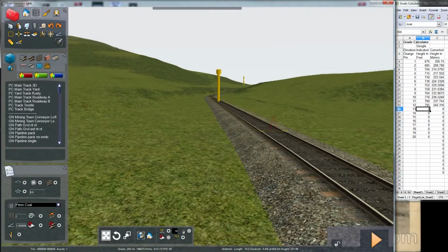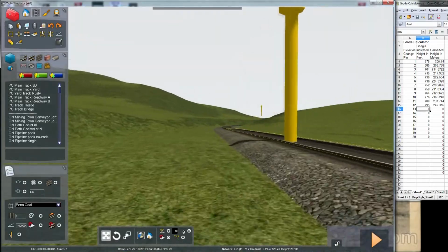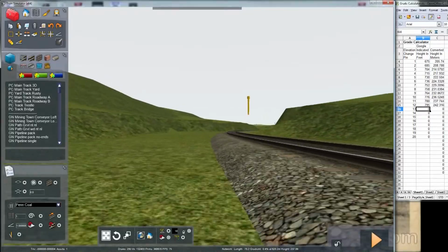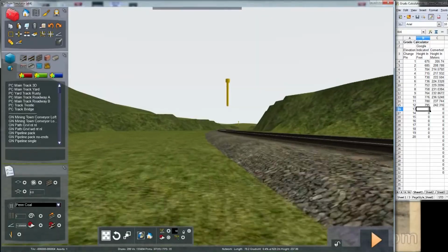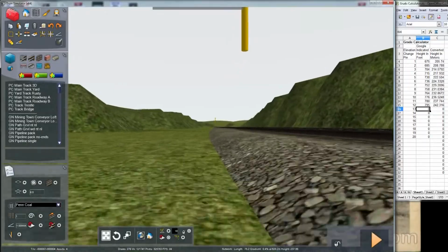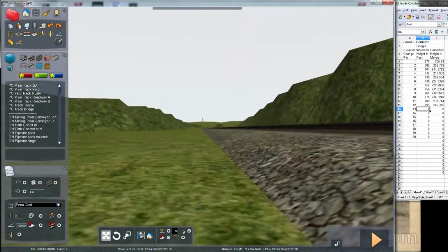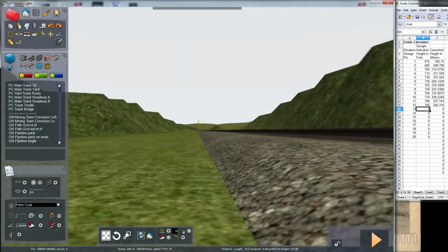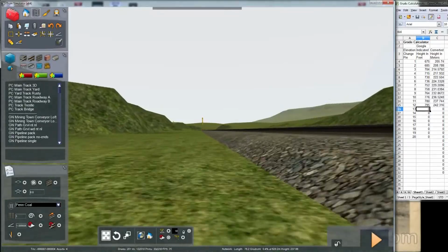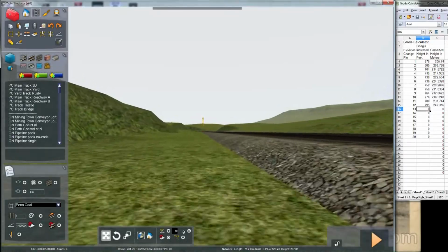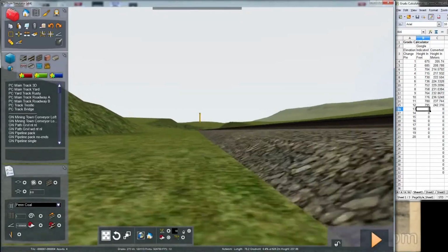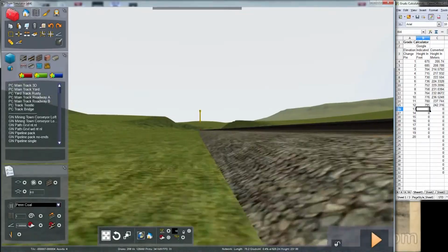We may not be in exactly the right spot with it, but I'm still constantly amazed at how these measurements take place. But anyway, he would sit down on his cushion and he would sight down the top of the rail, and the men with the jacks and the jacking bars would jack the track. If there was a low spot, he would give them a hand signal and they would jack up until he felt like that elevation was correct, and they would stop jacking, and then they would hand tamp with the ballast forks the ballast in around the cross ties. That's what the old section men used to do.